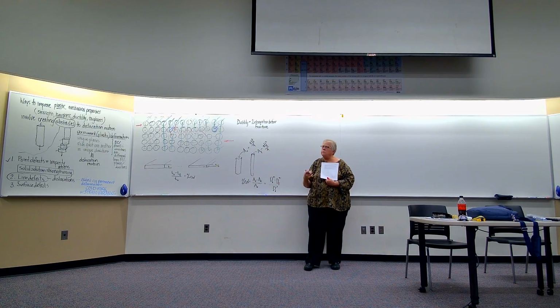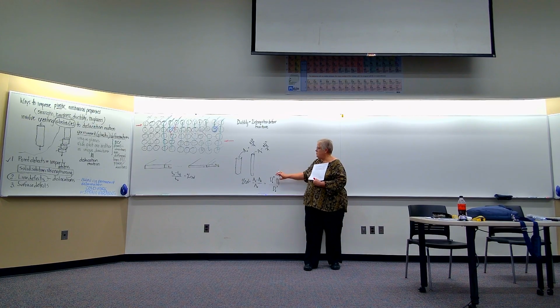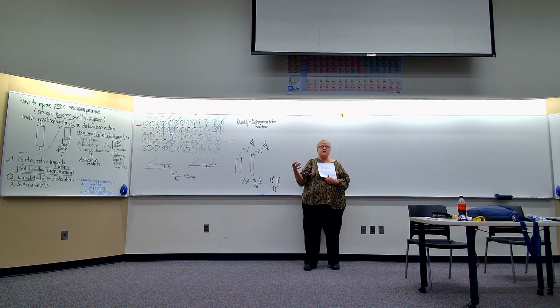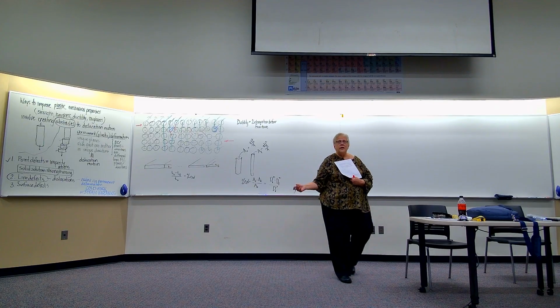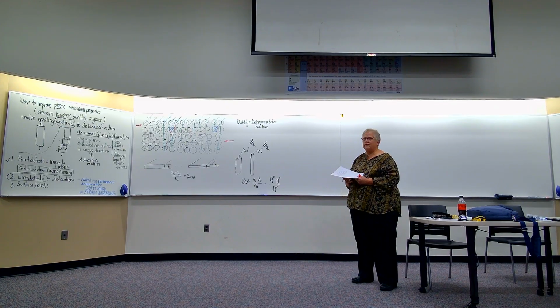So it is a characteristic: the percent that I could elongate this material before it fractures is ductility. The percent I have changed its shape is percent cold work. They're different, but it can be kind of confusing because you're thinking about something getting thicker or thinner, and percent elongation can sort of trip you up.